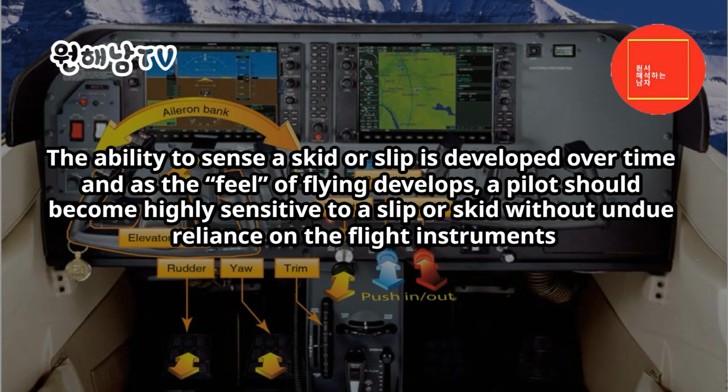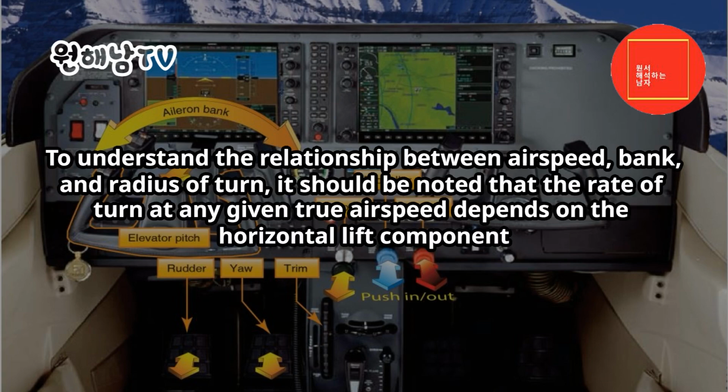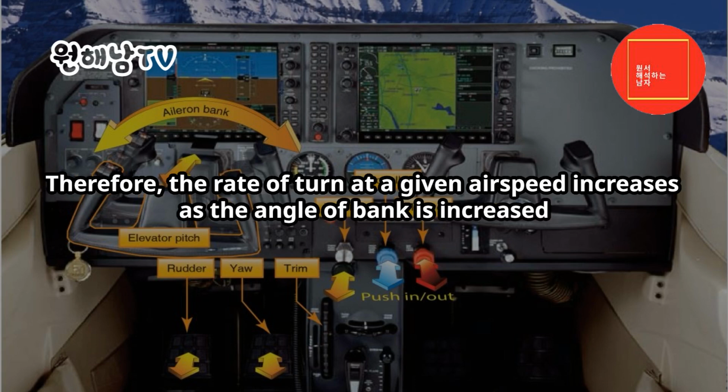The ability to sense a skid or slip is developed over time, and as the feel of flying develops, a pilot should become highly sensitive to a slip or skid, without undue reliance on the flight instruments. Turn radius. To understand the relationship between airspeed, bank, and radius of turn, it should be noted that the rate of turn at any given true airspeed depends on the horizontal lift component. The horizontal lift component varies in proportion to the amount of bank. Therefore, the rate of turn at a given airspeed increases as the angle of bank is increased.